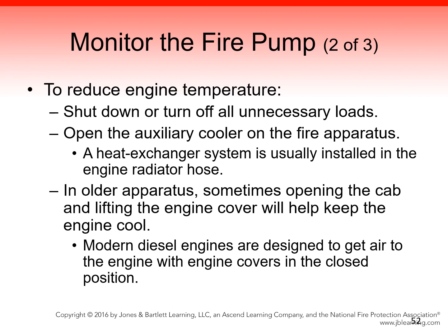In old apparatus, sometimes simply opening the cab and lifting the engine cover to allow more air to get to the engine will keep the engine cool. Modern diesel engines, however, are designed to get air to the engine with engine covers in the closed position. Opening the engine covers in diesel engines will change the airflow and could negatively affect the operation of the engine significantly. Follow the steps in Skill Drill 11-5 to operate the auxiliary cooling system.